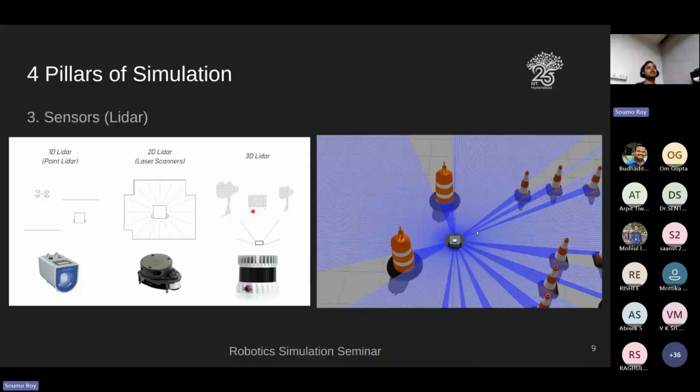Now, two-dimensional data can be very restricted, right? Because think about this cone that you can see here. Chopping a cone at a two-dimension layer, you know that the cone corresponds to this height. But you only know what the obstacle is at this height. What you don't know is the height of the cone, right? If the cone has a space down, or a space up. So that's why 3D LiDAR as a sensor modality comes in.